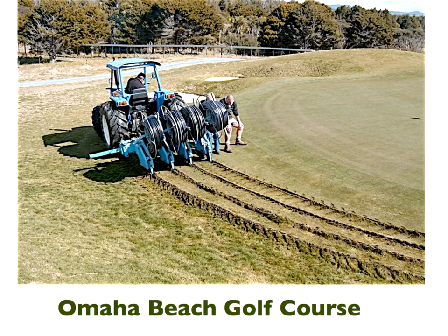On this particular project, we never did the greens. And this was on my personal recommendation not to do the greens. I discussed it at length with the engineers. Firstly, most greens aren't level. They go up and down. So you're going to have all sorts of risks with vacuum and sucking sand back. We can't put air vacuum relief valves in the middle of the green. You know, they don't like that. Then these golfers, I don't know, they're not rational people.